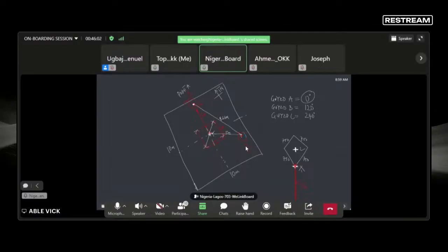What is wrong with this diagram is I said the tip of the base plate should always touch the 5 meter line. Now look at what I did here before. But in reality, this is how your setting out should look like. Are you seeing the difference? The tip of the base plate should always touch your 5 meter line.